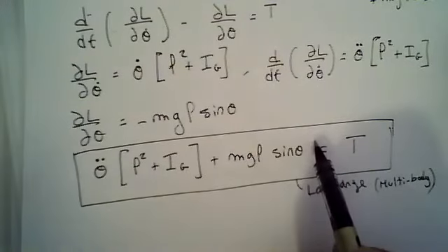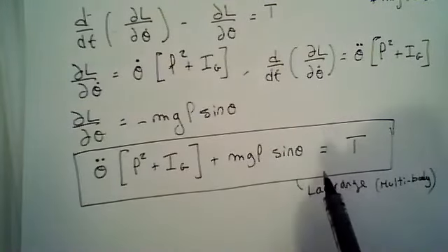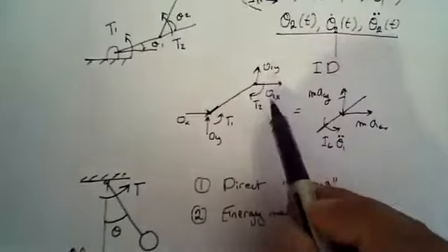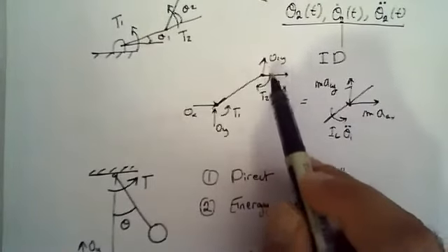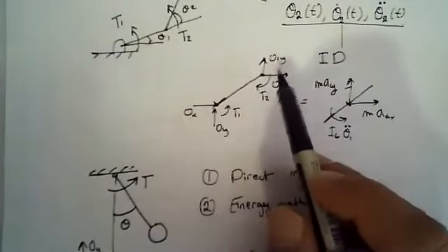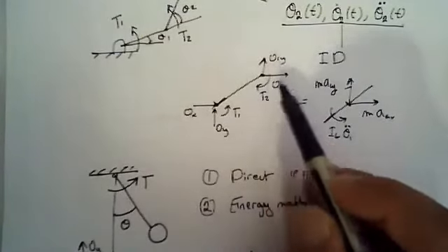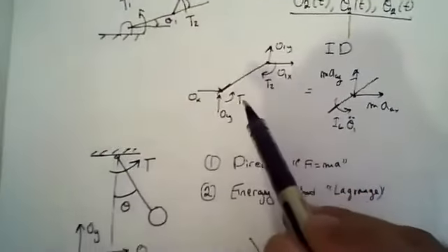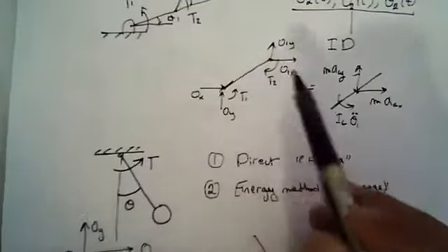But for multi-degrees of freedom systems, Newton becomes very difficult. Why? Because you will actually have to incorporate your unknowns, right? O1X and then O1Y, and when you sum the forces, for example, on the second link, you will have a lot of internal stuff that you have to solve for before you can solve a direct relationship between the torques and thetas.